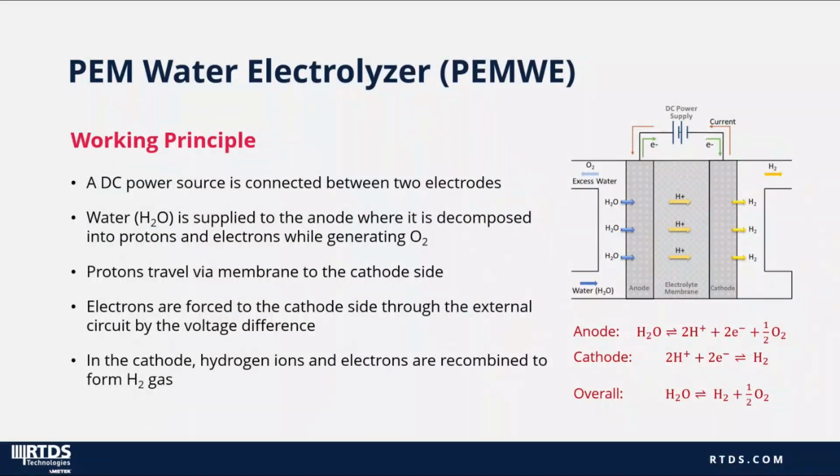In this slide, you can see the PEM electrolyzer model. Electrolysis is the opposite of the fuel cell operation. In this technology, an electrical DC power source is connected between the two electrodes, and water is given to the anode of the cell.